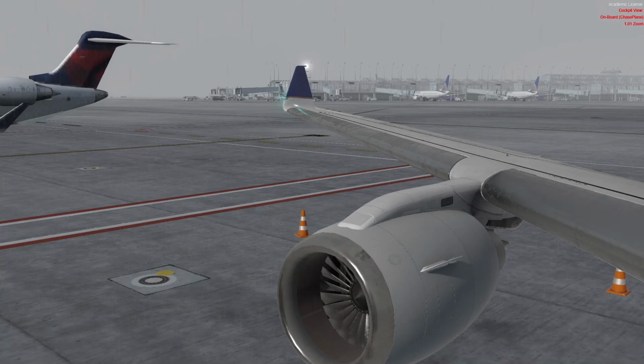The engine's heating consists of hot air heating the engine cowling ring. You can see that here, the engine cowling ring, that silver part here, to prevent ice from forming there, disrupting airflow and potentially breaking off into the engine itself, causing damage.